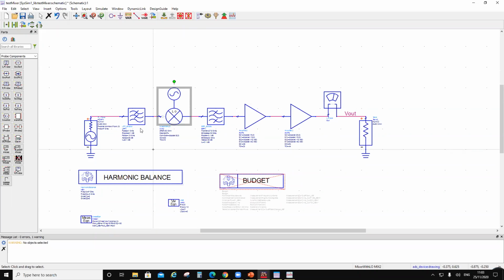Now this gain you are dividing in different stages. So mixer realistic gain around 8 or 10. Gilbert cell is going to do this. Now, if I was to do a balanced mixer, it will be like minus 8 or minus 7. So in this case, if I want a gain of 40 or 50, then it is minus 8 over here. Then the remaining gain has to come from the gain stages over here, right?